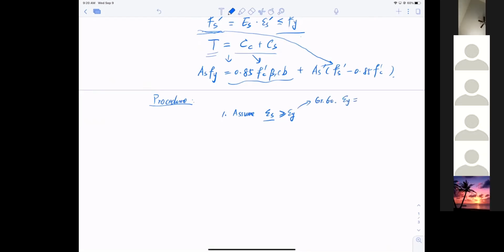60 ksi. That's the strength, close. So Fy equals 60 ksi, divided by Young's modulus, which equals 29,000 ksi. Roughly equal to what? 0.00, I'll give you a hint, 2, plus 2 digits. Let me try it. Okay. 0.00207, right? That's good.